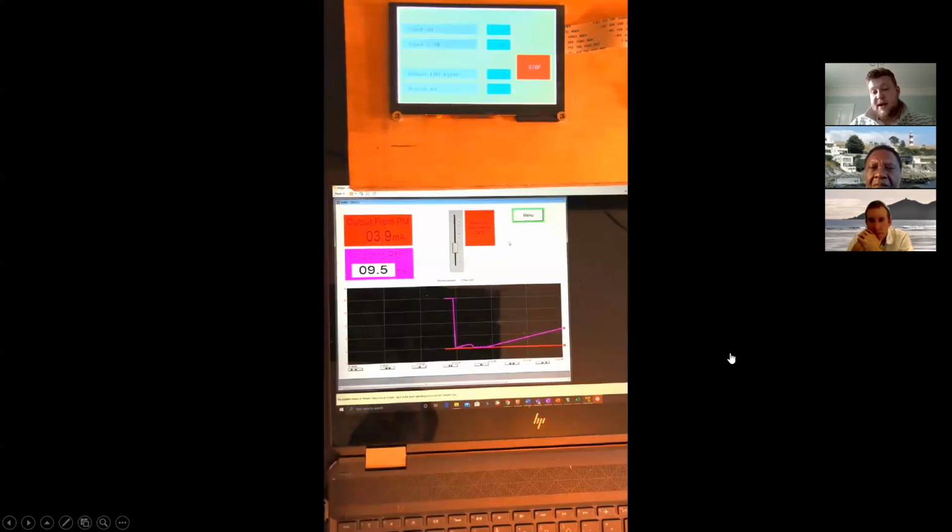You can see the pink line climbs until roughly 10 to 12 milliamps, where then the red line will start to print out the characteristics of the curve. Obviously, like I said, the normal curve is exponential, so it only changes a little bit at the moment. As you can see from the top, the output from the process meter is just starting to move from 4 milliamps to 5 milliamps now.